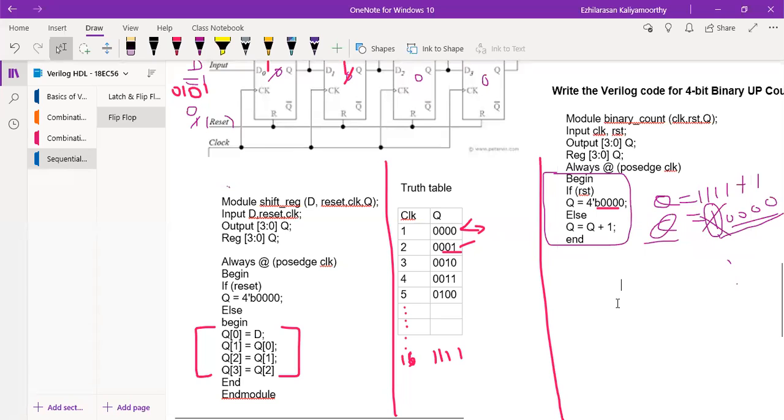Did you understand the question? What did I say now? As the question says, 15, it is a down count. 15, 14, 13 because minus 1 is there. So our count will reach 0. After that, again what will happen? 0 minus 1 will come. It is minus 1, correct? That's a down counter. Again what should I get? After 0, again I should get 15, correct? Yes, again 15.